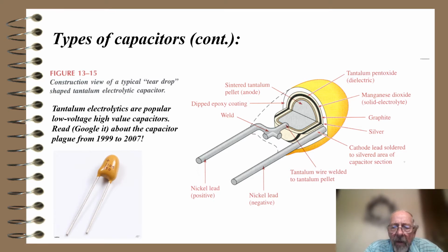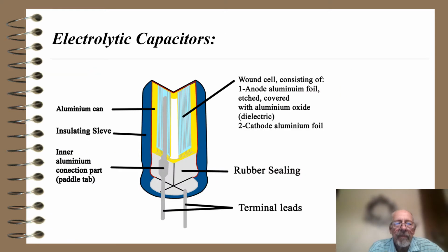Somebody patented these types of capacitors, and somebody tried to copy them, reverse engineer them, and it turned out that the dielectric that they came up with was not stable, and so a lot of equipment was built with the cheaper copied tantalum capacitors, and it turned out that they all of a sudden would go bad after about 6 months of operation and cause the equipment they were in to have problems, if not fail.